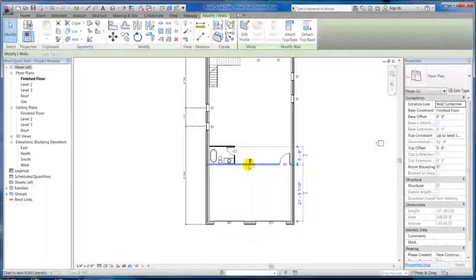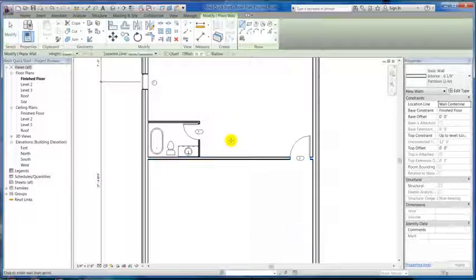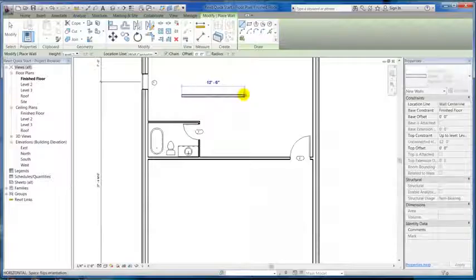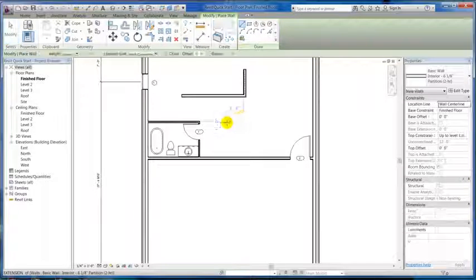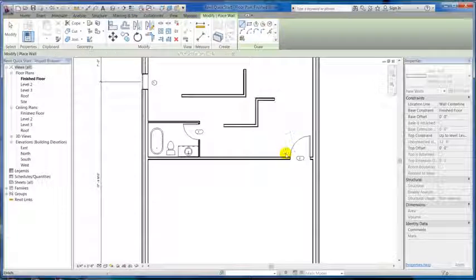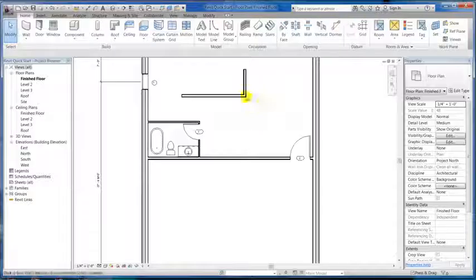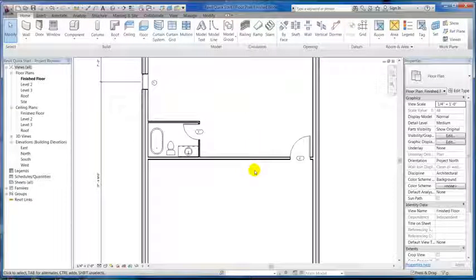If you click on an element, like that wall, I can right click and go to create similar. And that will let me create another one of those walls. I have that exact same wall and I can create it. Well, to me, right clicking took too long, so I just type in CS, no enter key, no space bar, just CS, and that's it. And I'm right into create similar. So that's how you do your keystrokes. And right now, instead of hitting the delete button up here, I'm just hitting DD for delete. That's my keystroke that I set up for myself. Seemed to be pretty easy.